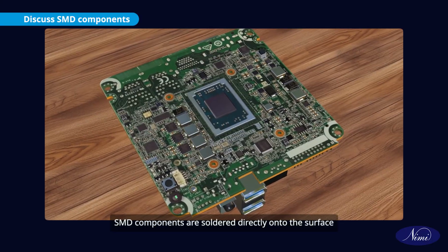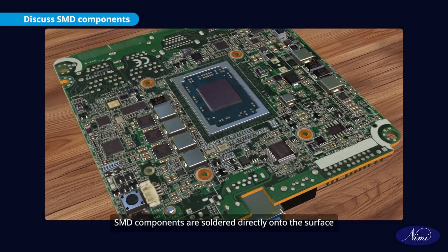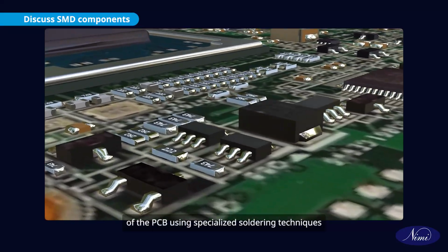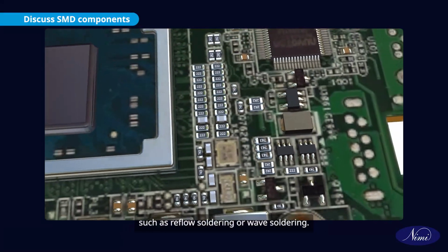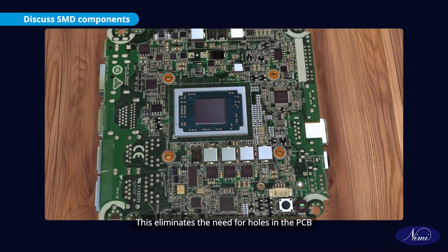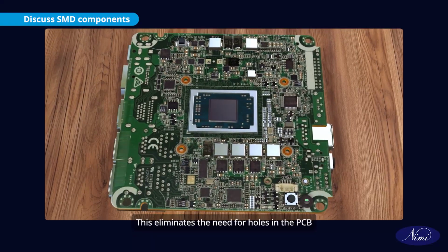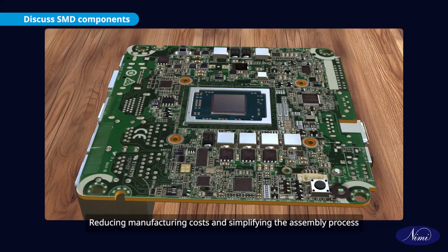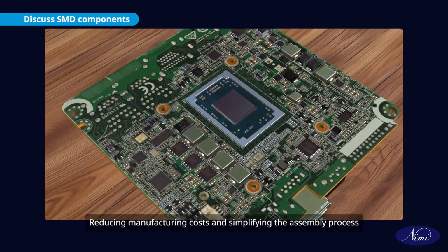SMD components are soldered directly onto the surface of the PCB using specialized soldering techniques such as reflow soldering or wave soldering. This eliminates the need for holes in the PCB, reducing manufacturing costs and simplifying the assembly process.